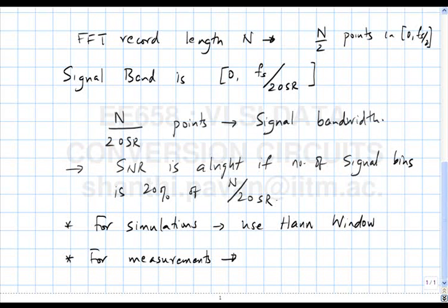And if you want the signal power to occupy 20% of the number of bins, then for the Blackman-Harris, what do we find? The signal occupies about 9 bins or so, 4 bins on each side. So 9 bins, and you want to have at least 50 bins in the signal band, right? So 50 bins in the signal band basically means that for an oversampling ratio of 64, you will need 50 into 128 or something like that, some 6,000 odd points.